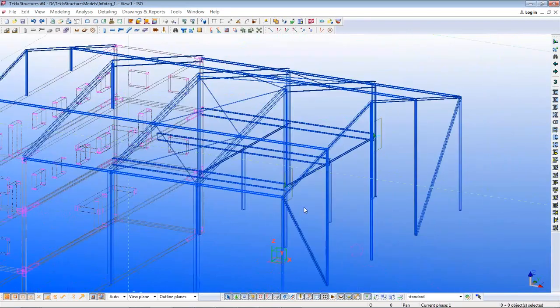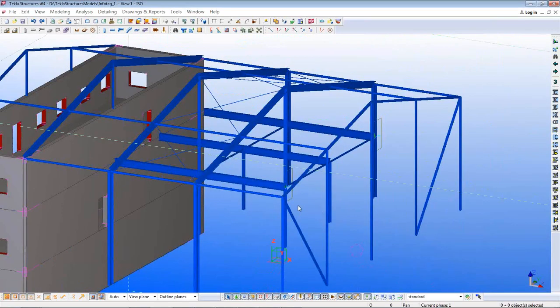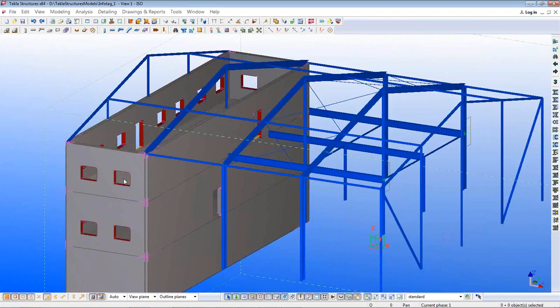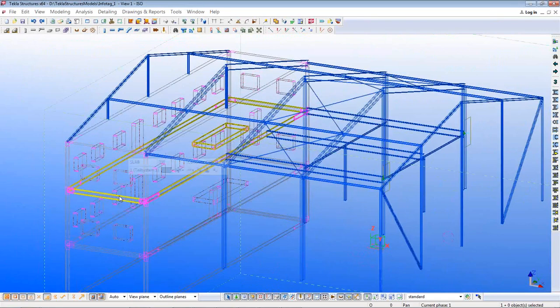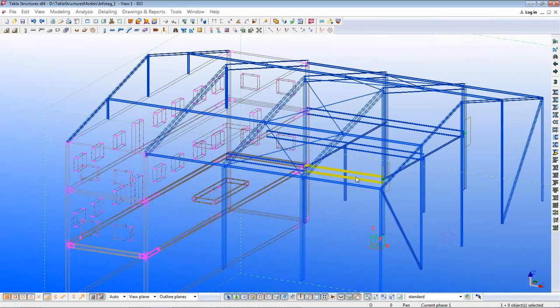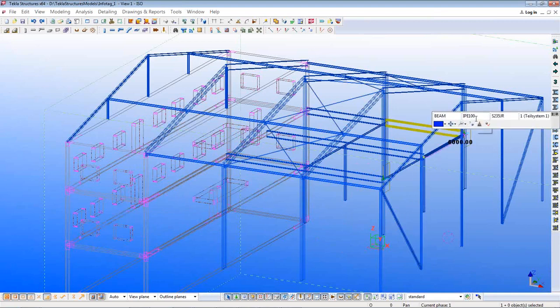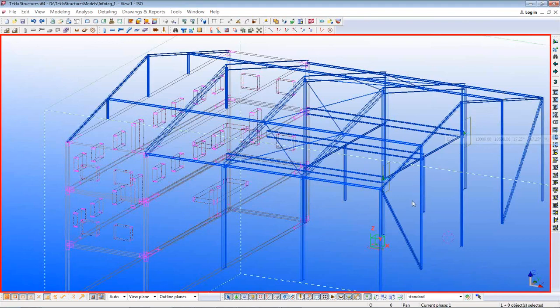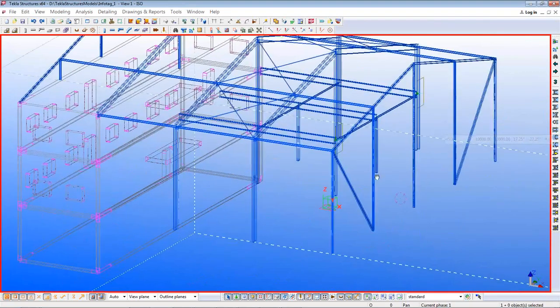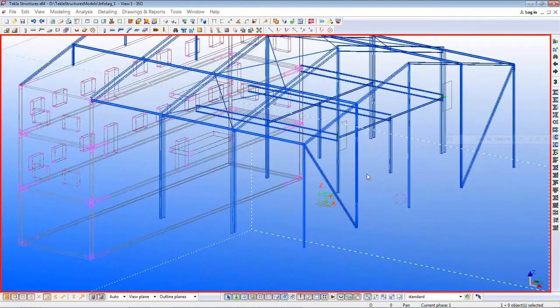So you can basically work in parallel on your structures. And if I click here, there should be a different thickness. There's 300 here as well as here, and we have different cross sections also, like here, which is an IPE 100, which maybe is too small. Maybe I want to change it. We can do it anytime and do it the same way as I showed.